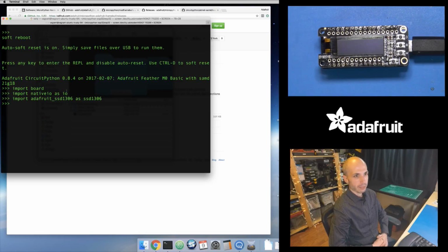So, previously we saw error framebuff module not defined. Now it worked because I added this framebuff.mpy, which is an implementation that has pretty much exactly the same interface. So it should be compatible and should work. It's just going to be a little bit slower.